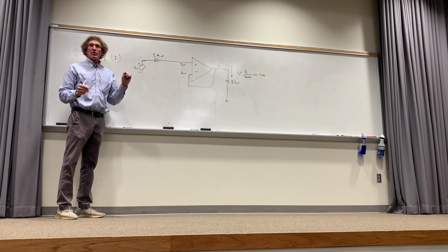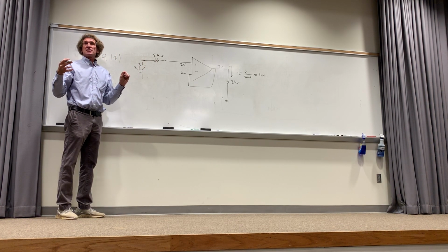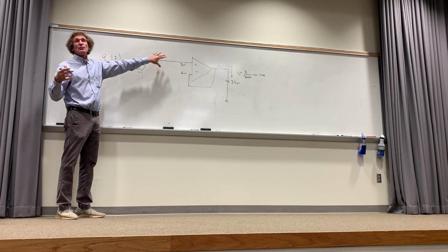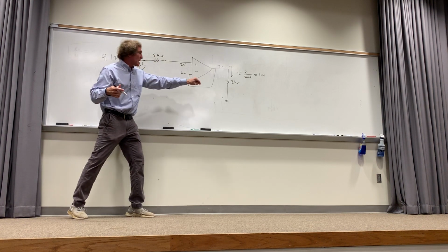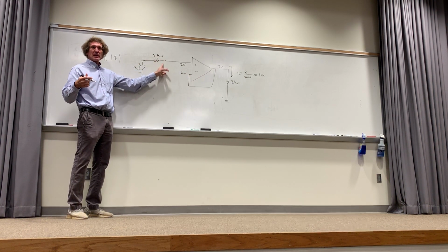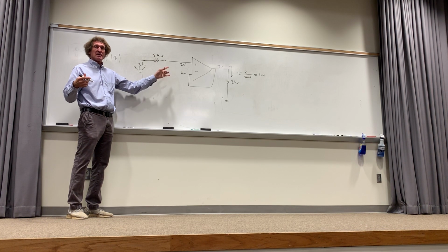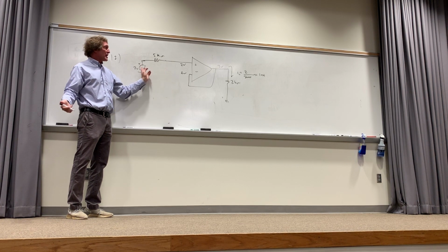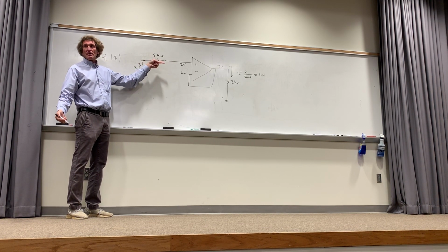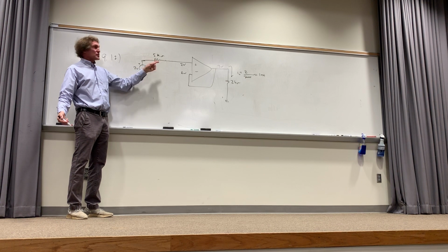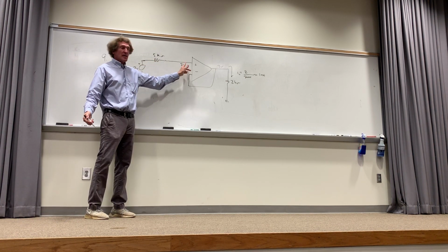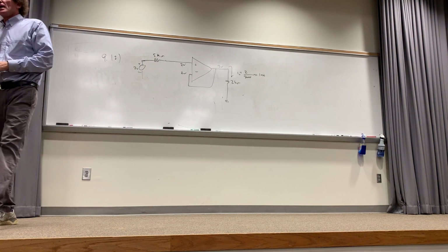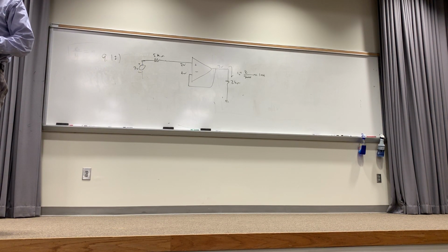Now if I got 5 mega ohms there, and this represents some sensor, if you can follow, the way I need to monitor this sensor is with a 2K resistor. You see, most of the voltage is developed here. If you just put 2K down to ground and try to measure, you can't. So what you need is a follower circuit. Now in this circuit, no current could flow there, right? So that 2 volts is right there. That 2 volts is here and here, and therefore now you can get a lot of current. You can get power, and it's measurable and it's usable. Follow me? That's a follower circuit.